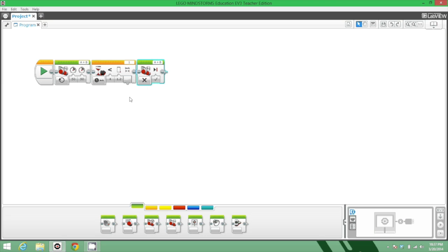Unfortunately, I think the next sensor that I want to use, the color sensor, needs to be a little closer than 1.2 inches away. But the distance sensor is not sensitive enough to get close enough. So what I'm going to have it do is, after it realizes it's 1.2 inches away, I'm going to have it go actually just a little bit further.